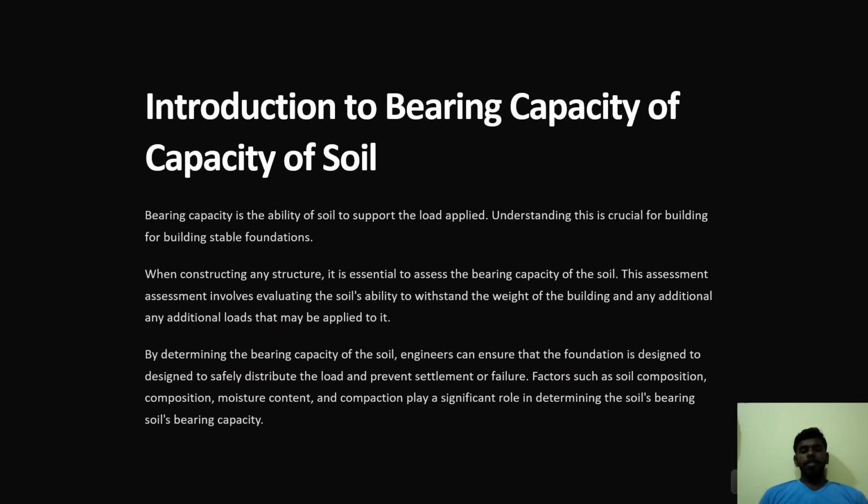By determining the bearing capacity of the soil, engineers can ensure that the foundation is designed to safely distribute the load and prevent settlement or failure. Factors such as soil composition, moisture content, and compaction play a significant role in determining a soil's bearing capacity.